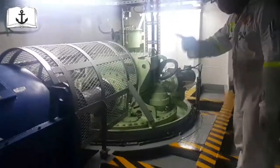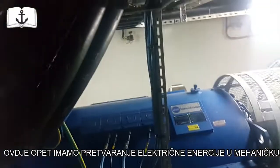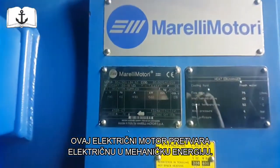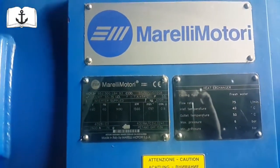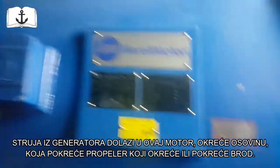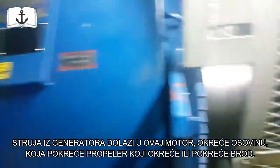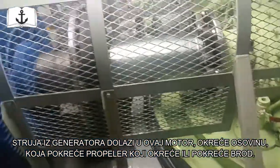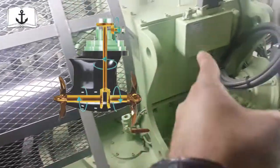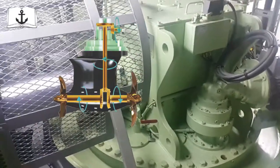Okay. We have here conversion of the power back to mechanical force, and there is a coupling. So this is where it happens. This electric motor. You can also mention that it's a 90-degree thruster. So basically, here is the actual shaft. Wait. So, the electric motor is here. All that power from the generator is coming to this motor. Then it's running. This is the shaft. The shaft is turning. There is a 90-degree gear. And the shaft is going down to the thruster, to the sea, and it's moving our propellers.